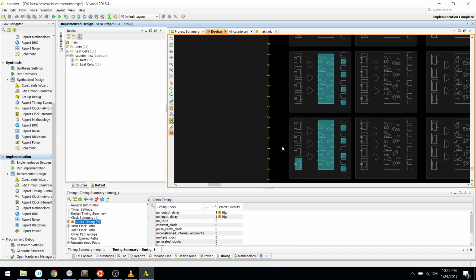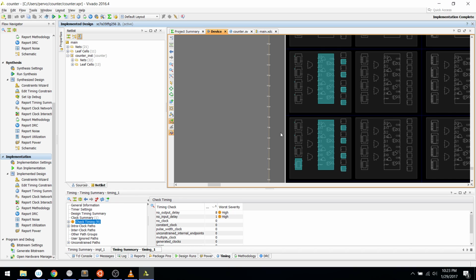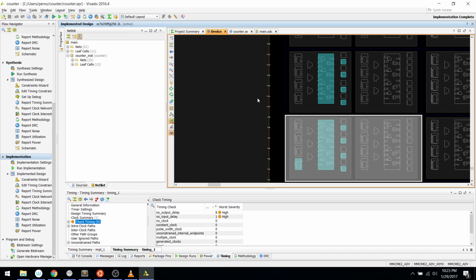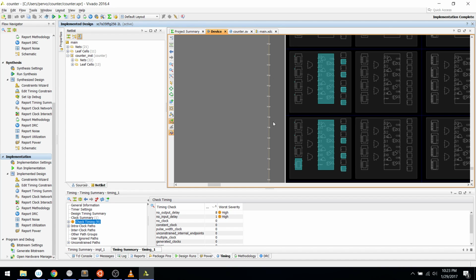It's actually changed the design and how it's laid out and synthesized based on the timing constraint. So do you remember previously the basic design was to use a lot of LUTs, in fact at least one for every counter bit, with a lot of inputs for each of these LUTs, all the previous lower bits. Basically what it's decided is that now we've actually given it its deadline, the timing constraint it has to meet, it starts using the slack to do more area efficient optimization. So previously it was using a ton of LUTs and I think three slices total. Now it's using only one LUT, and it's using these adder chains that I mentioned, or the carry chains internally.